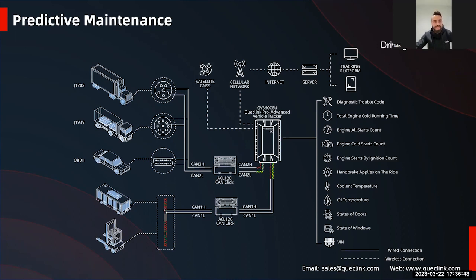In this application, the device can save your money by identifying issues with your car just by seeing the MIL light and getting the DTC codes, then seeing what the problem is by interpreting and translating them. Imagine you have a fleet of 1,000 or 10,000 vehicles. You don't need to take each car from this fleet to your technician. Just from the device, you can know what the problem is. You cannot take a car to your mechanic just for a few things, right?